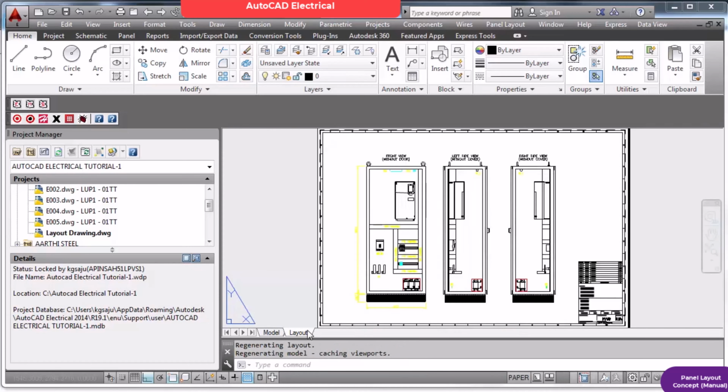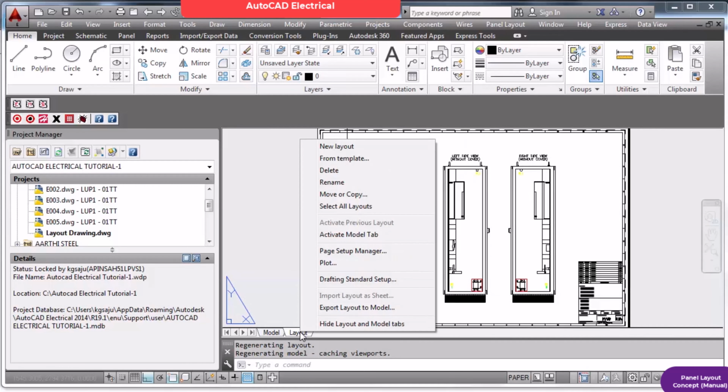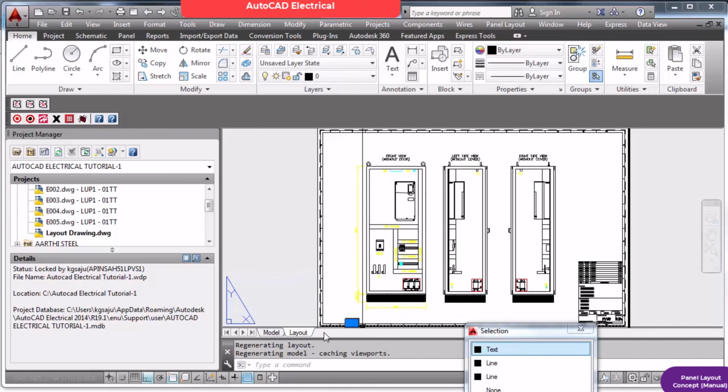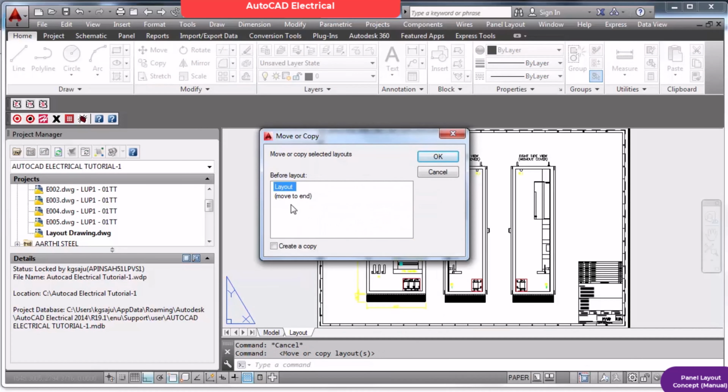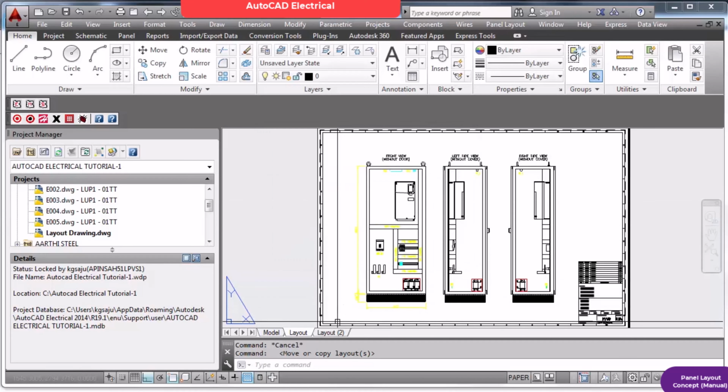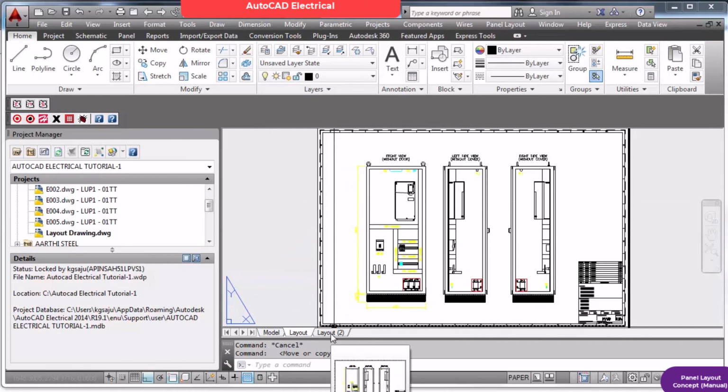Now this is a perfect drawing. If you make any modification here, now I am going to delete this drive. Go back here, the drive is not there. Undo, here it is. So this is how you can make use of this paper space for your layout drawings.